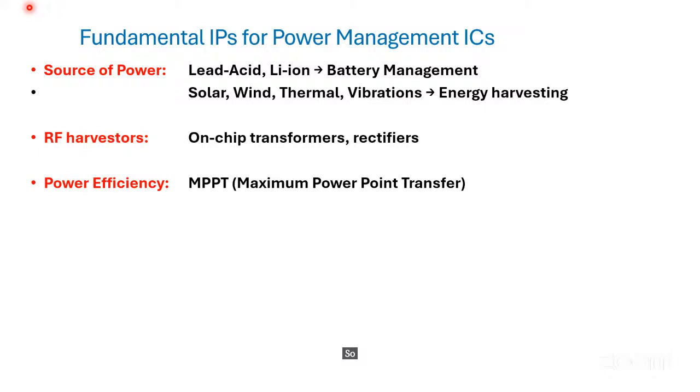So that is why it is very important to always keep the system, or design the system, at the maximum power point transfer, where the efficiency can always be maintained high while you're transferring the power to the load.